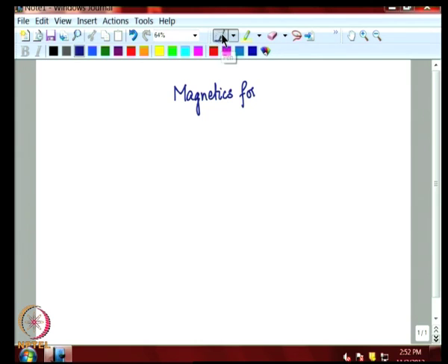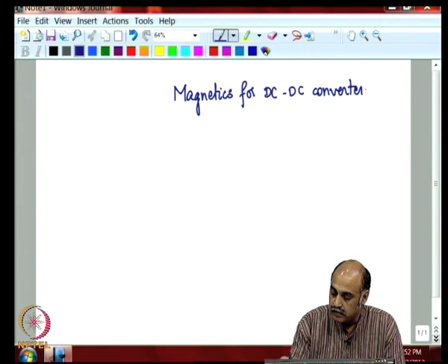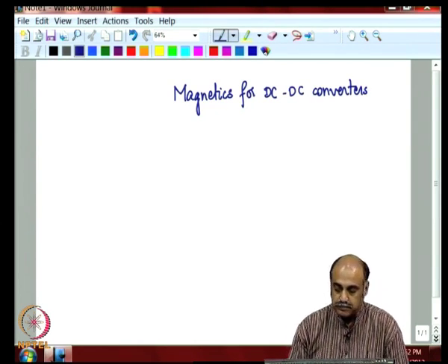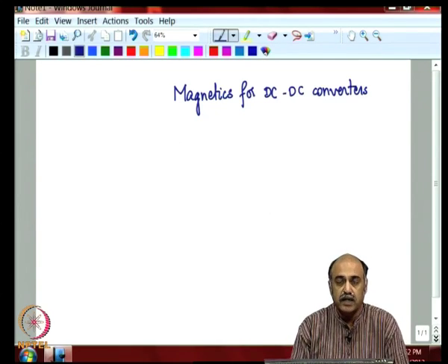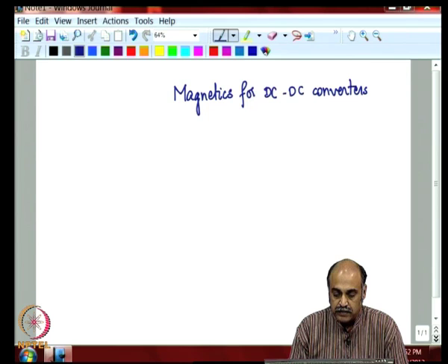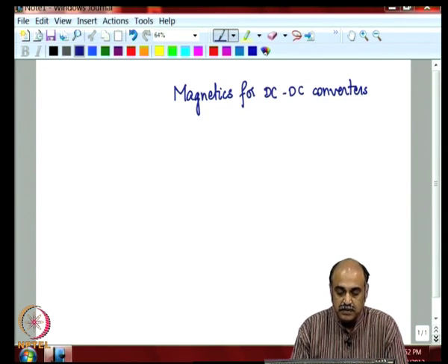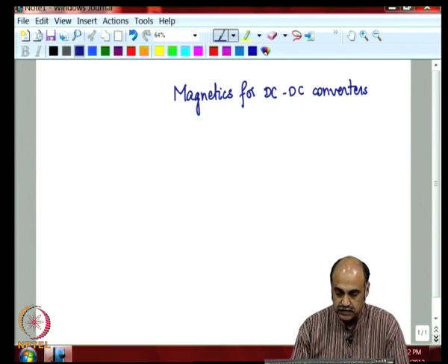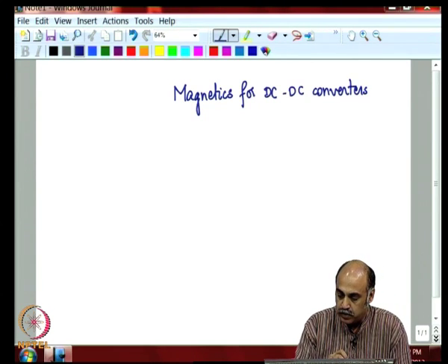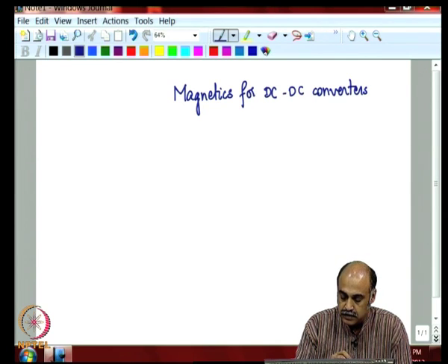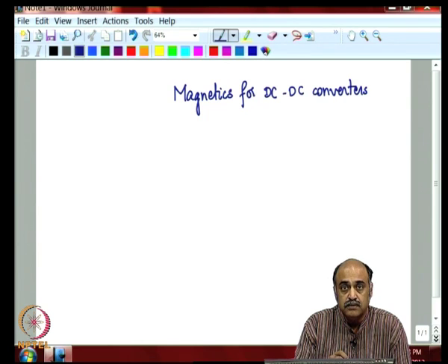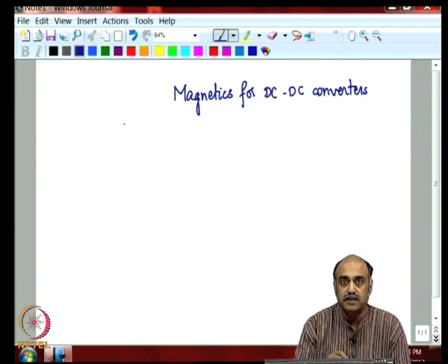However, once a design is performed, the magnetic components, being passive, are very robust. So, nothing happens to them, unlike the power semiconductor switches or the capacitors, both of which may blow once the rating is exceeded. In the magnetic components, the only rating that can be exceeded is the currents and the saturation levels, which will cause other components to get damaged, not itself.